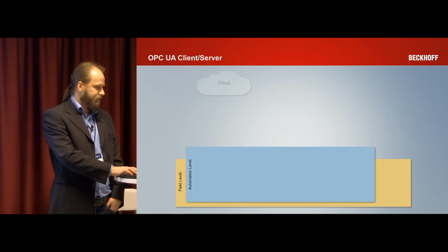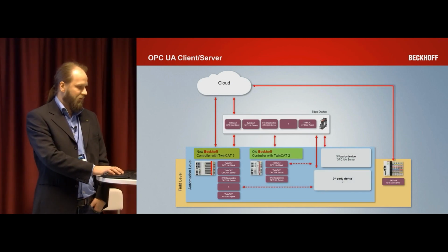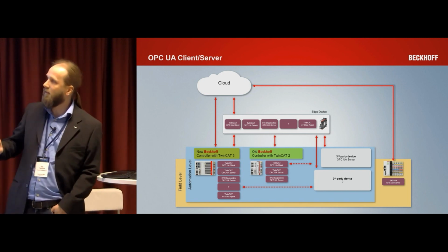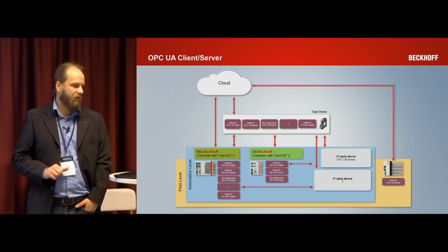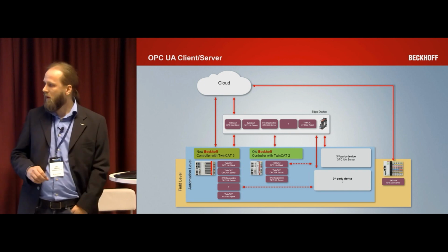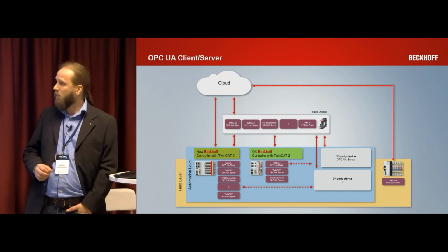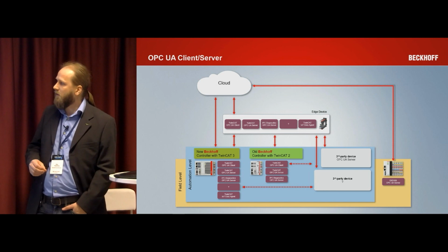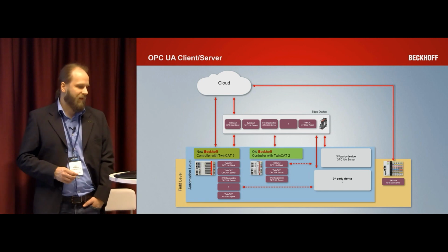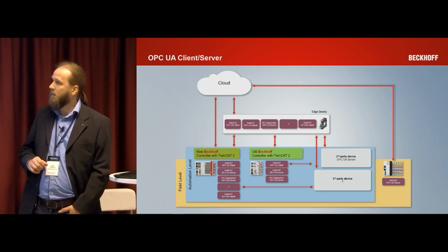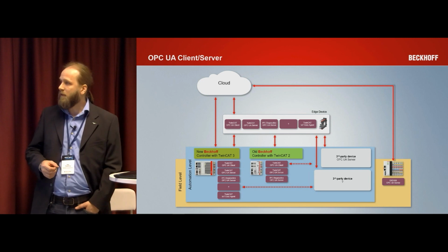The first possibility is, okay, I need to move this slide so that you can see everything. There is this yellow box, which means the field level and I/O system. We have this IoT coupler product, so that you can directly install our I/O terminals with it, and it automatically uploads the data to the cloud, and it provides an OPC UA server. So you don't need to program any PLC code. You can just use a web browser for configuring the device.